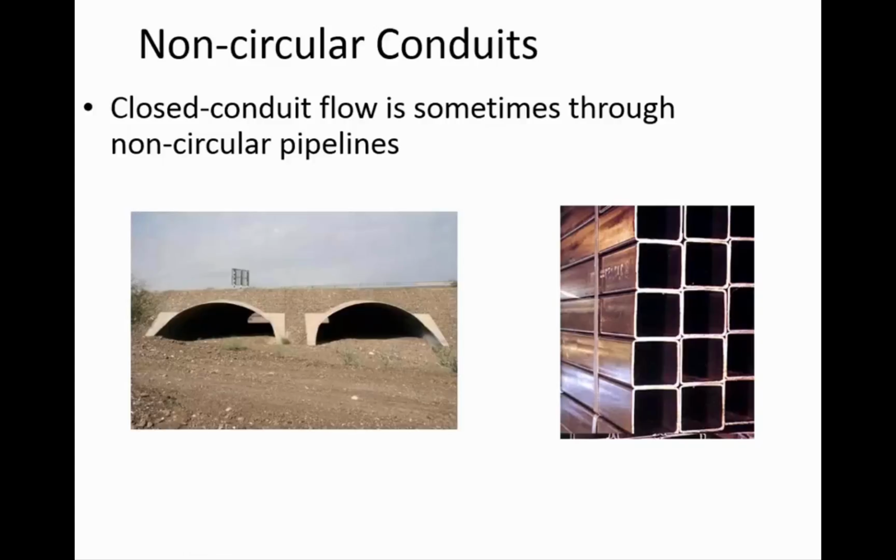It's runoff flow that's coming out of the mountains, and it doesn't rain very often there, but when it does, it's really an enormous flash flood. And for some reasons that we talk about in hydrologic engineering, you really don't want water going over the top of the road, at least not for too long. It's okay for storm flows to overtop occasionally and for a few minutes, but if there's overtopping for too long, it could actually wash out the road entirely.